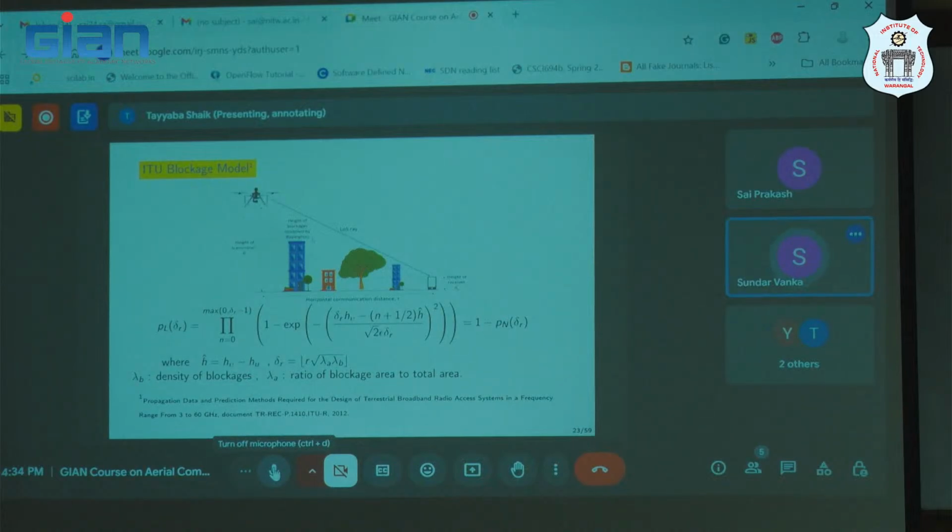People are talking about terahertz. Terahertz will have even more of an issue, which is why we are limiting it only to the room, only at the access point. Right. On a slightly different note, the future way in which we'll probably communicate will mean using different bands for different distances. So within a room, maybe you'll use terahertz. That's what the new radio says, but we don't know how it goes. Only time will tell whether there are use cases that use it. That's a problem. Because at the back end they are pushing everything into fiber, so they're assuming the front end can go.